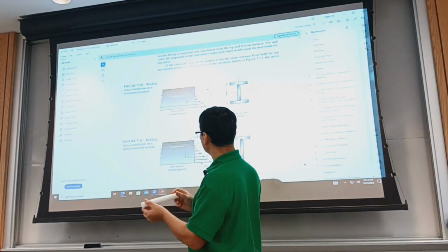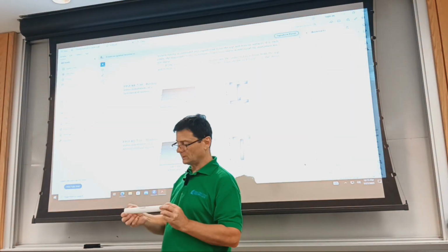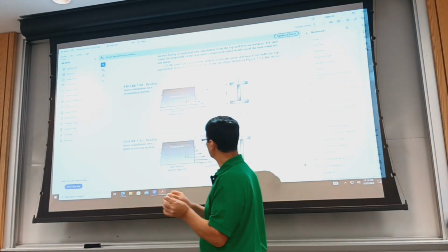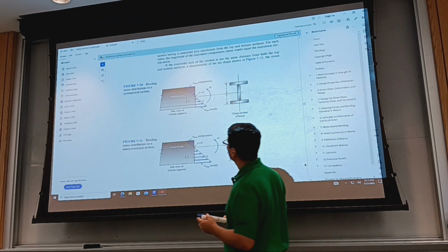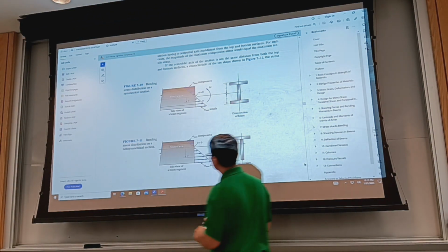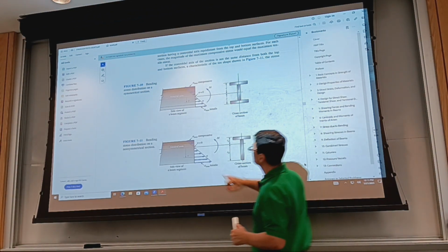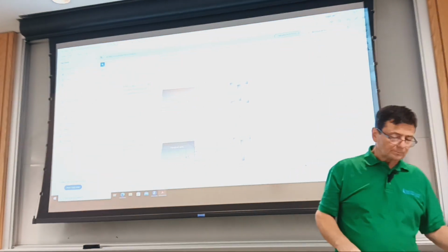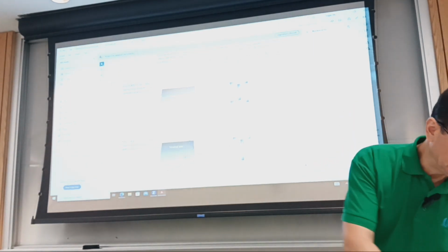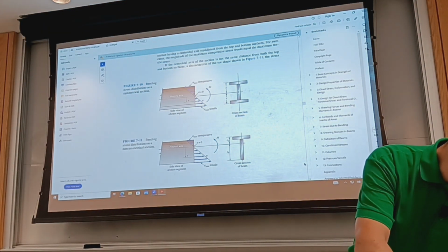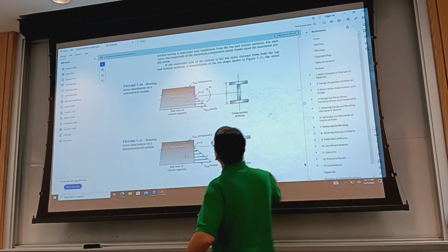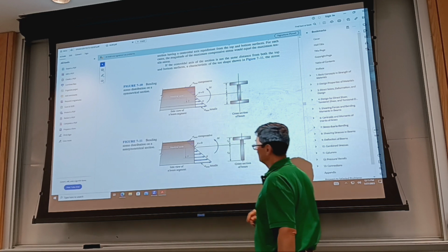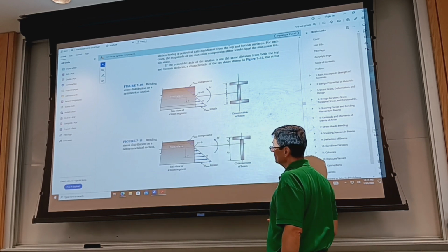For a beam that is bent with a positive moment, that will be a smiling beam, as we keep on saying, at least locally. So I have compression on top, tension below, and it goes through zero at the neutral axis. Now, in addition to that tensile and compressive stress, we also have stresses that develop, and these are due to the variation of the moment.